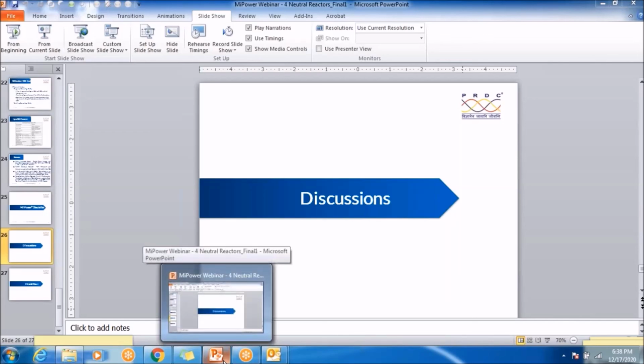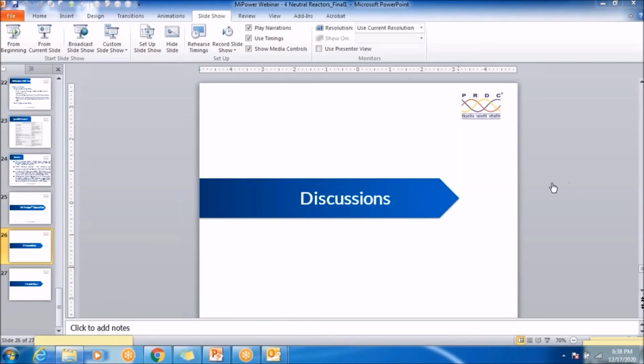But definitely sometimes if you just go with the thumb rule, in some cases it may lead to the resonance point. Maybe again you may have to change the NGR value to a different value, because above 16%, maybe you have the successful auto closing phenomena. But at 16% exactly, if there is any resonance problem, I can go for 25%, right? Then the 25% value I can use. So where resonance is not there, and also the main objective of the auto closing phenomena is fulfilled.